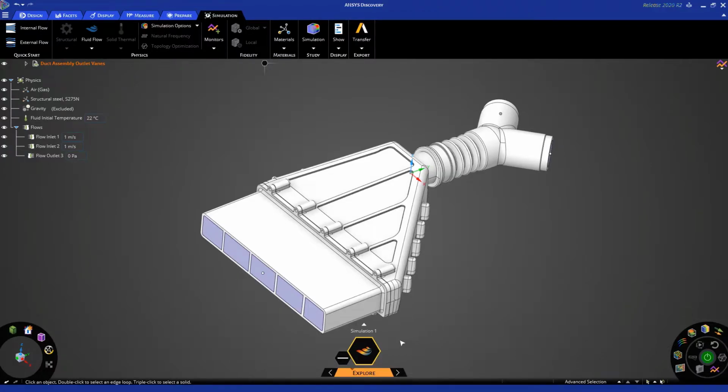Now, down at the bottom, you'll notice the simulation information display has various icons which help you understand what's going on. So it shows you the fluid flow symbol or icon, but it's also been colored to show that in addition to fluid flow, we're also solving for temperature because of the different temperature conditions that we applied at the inlet and outlet. Okay, so this is pretty much it. Let's click the green solve button to get started.